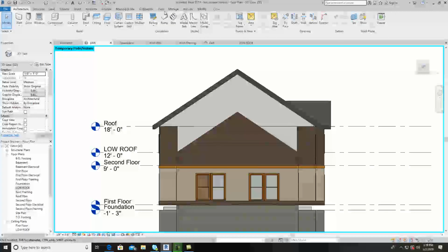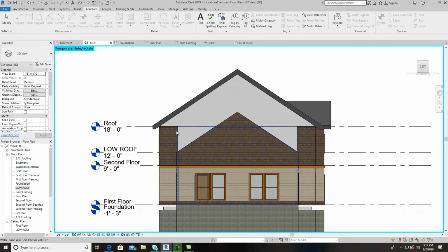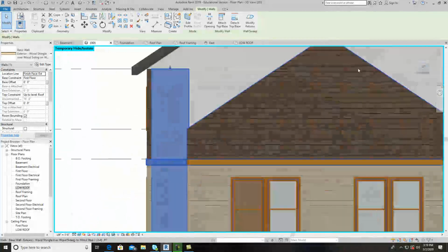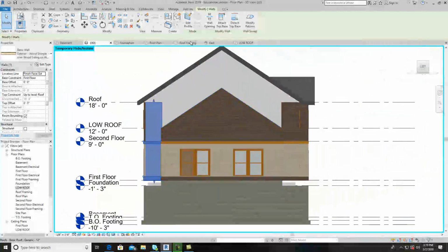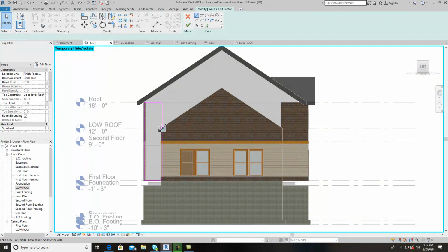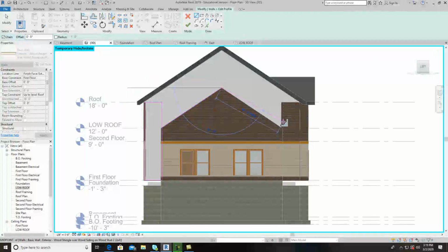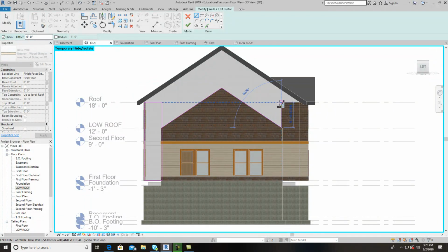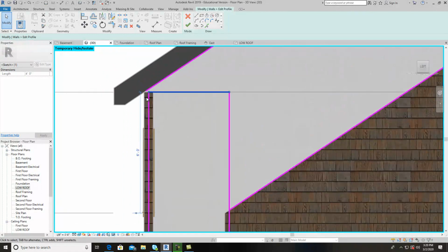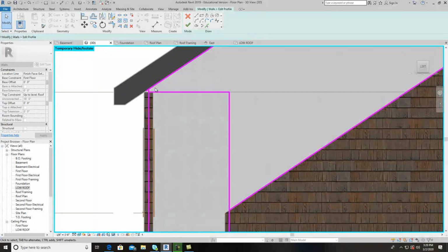And now, not annotate, but actually click on this wall again. Make sure I got that wall selected, and I do. Turn around, look. And what I want to do is edit my profile of that wall, and I want to let it follow along this. Now the book might do it a little different than I do it, but this is the way I've done this for years. So you got to make sure that these things are put together.